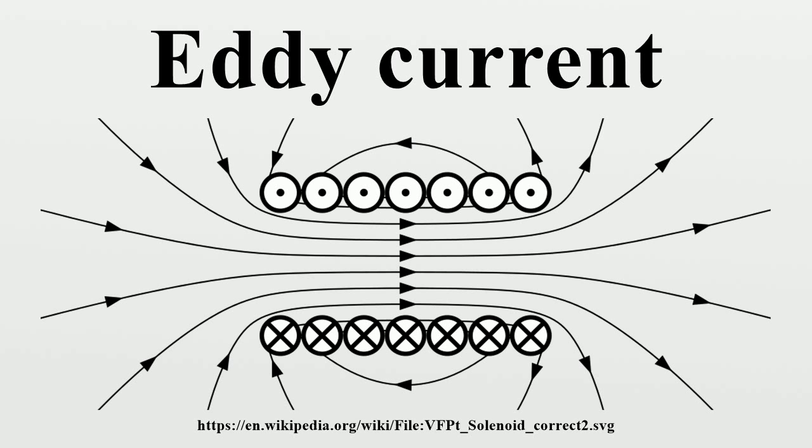The derivation of a useful equation for modeling the effect of eddy currents in a material starts with the differential magnetostatic form of Ampere's law, providing an expression for the magnetizing field H surrounding a current density J. Taking the curl on both sides of this equation and then using a common vector calculus identity for the curl of the curl results in an expression, from Gauss's law.